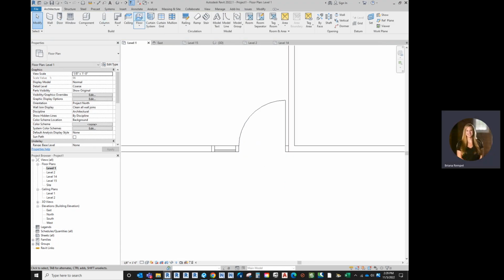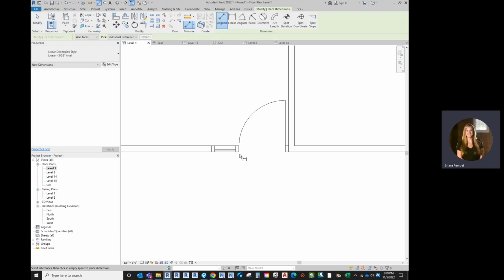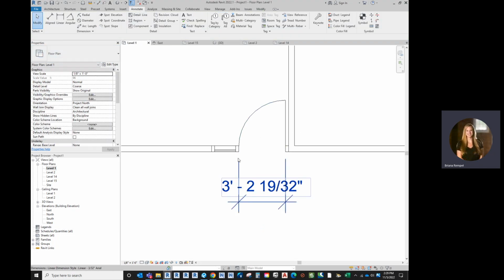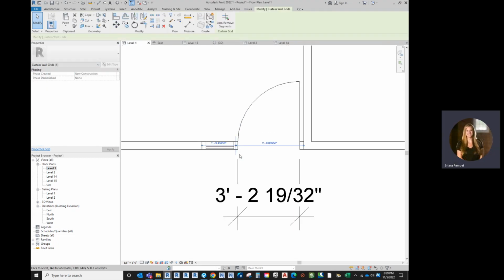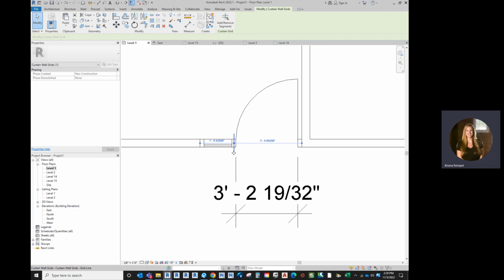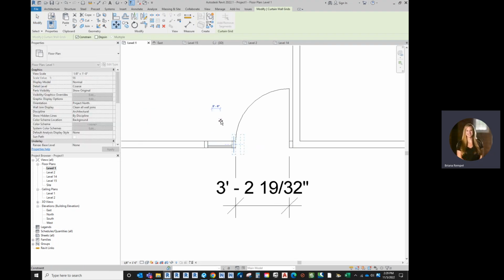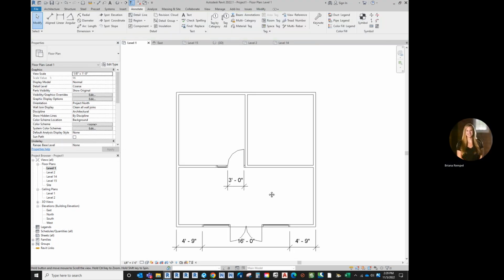And that's it here. If I want to control the size of my door, I can do that. Make sure it's a typical size. If it was going to be like 3 feet, because 3'2" is not a typical door size at all. To do that though, I need to make sure I select the grid, not because you're measuring to the inside of each mullion, so you can't just click on this and move it over. We're gonna need to actually select that grid and use the move command and do a little bit of math here to get it to that clean 3-foot door.